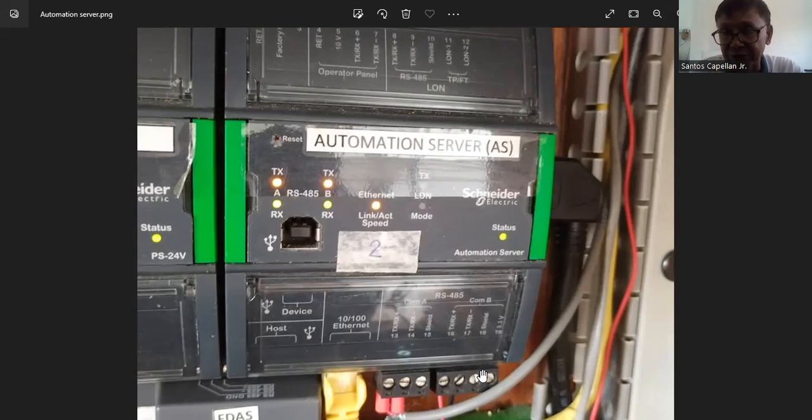When I say third-party system, actually, if you are a BMS engineer or a solution provider, first you need to study the project specification or the BMS specification. Okay. Then out of this specification, you will try to recommend the BACnet controllers. If you are going to use BACnet controllers, these will be the ones to handle all the control and monitoring of HVAC equipment, electrical, and low current systems. Okay, so these will be the controllers which you are supplying.